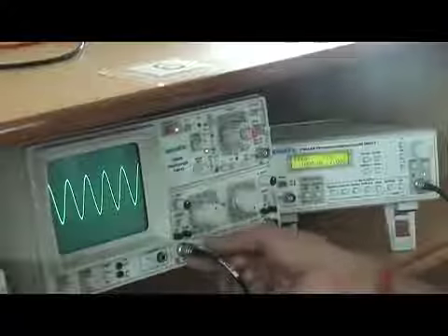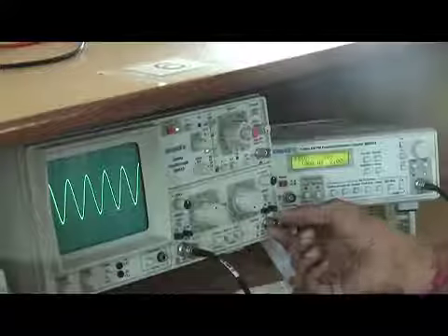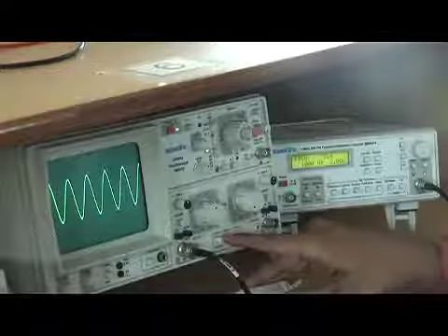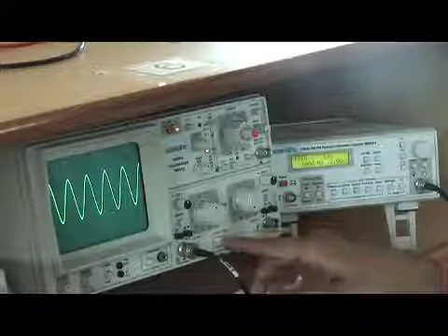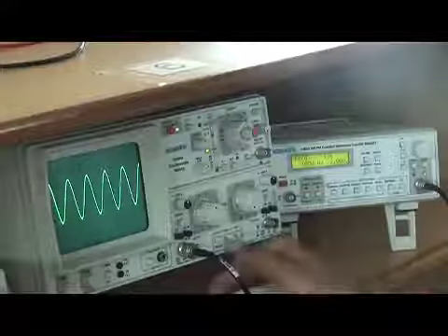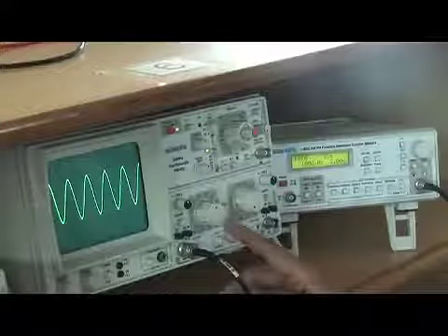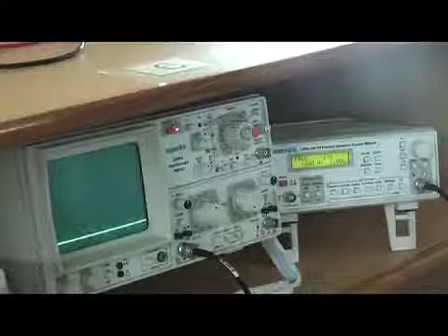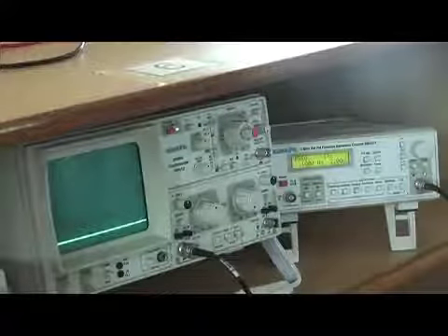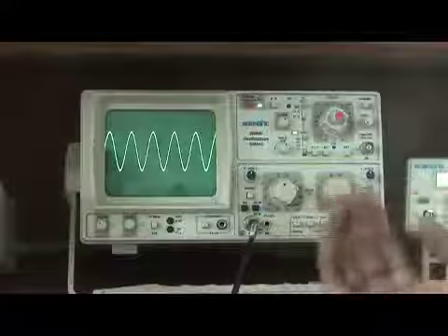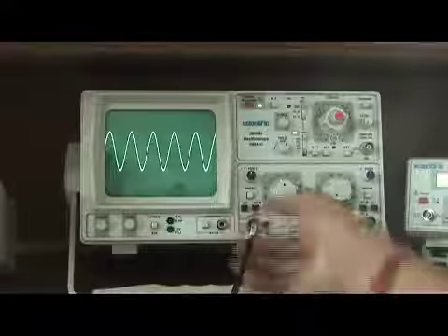Now coming to the CRO. CRO is the eye. It has two channels, which means it can view two different signals at a time. Right now I have connected only one. To select the channel, whether I am connecting my output to this channel or this channel, I have to use this button, where it is written CH1/2. CH means channel. When it is upward, it says that I am in channel 1. When I press it, it says that I am in channel 2. But right now I have connected it to channel 1, so I will keep it above, the upper part. So this is connected here.